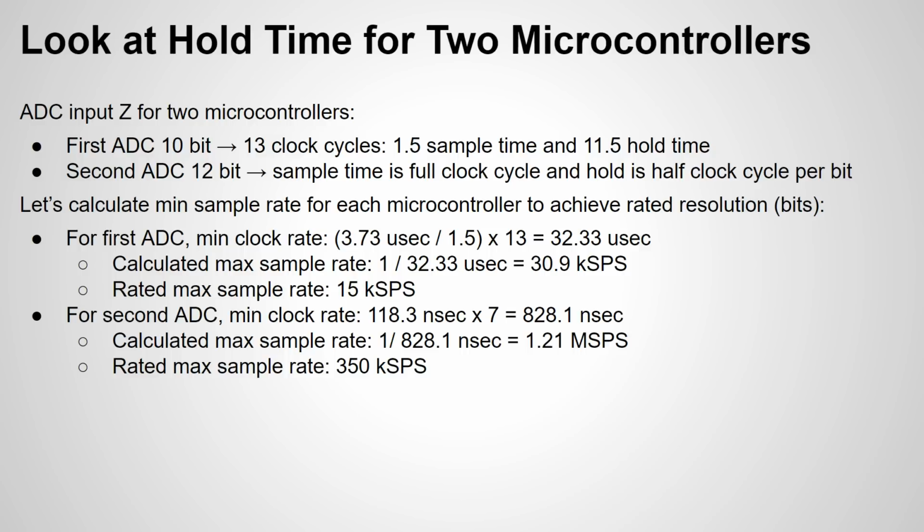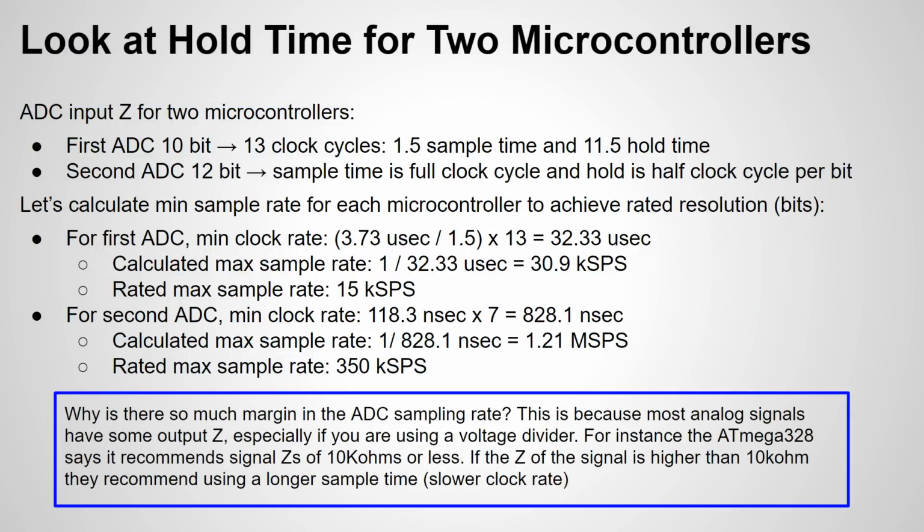Well, there's non-ideal aspects in there that they could be including. There also could be some kind of delay from one measurement to another, but often in free run mode there's not. There also could be limitations on how fast the successive approximation can work. But there's also a big factor, and I'll point that out. It's the input impedance, or how weak or strong the analog signal is that you're measuring.